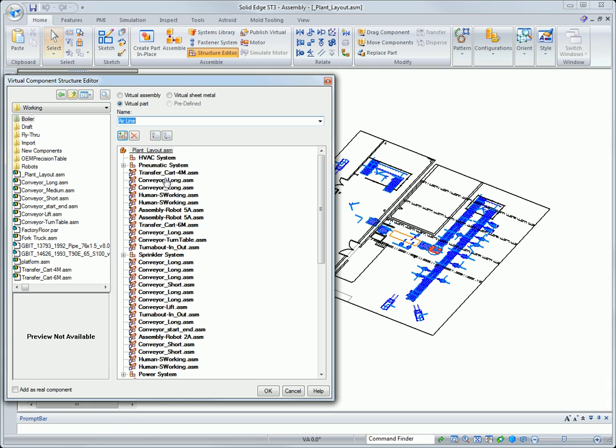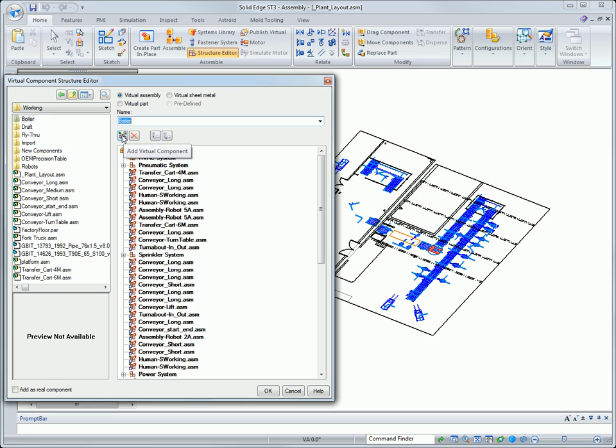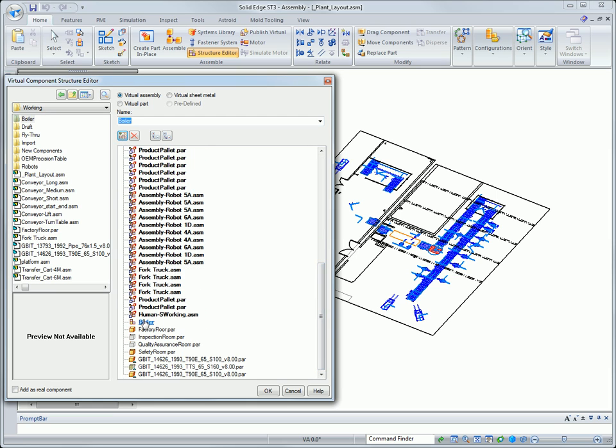If you're working on a familiar design, more often than not you'll have a good idea of what needs to go into the assembly. So why not capture this up front? Think about this. If you were asked to build a bicycle, you'd probably list most if not all the components. That's what virtual components is all about, a tool for jotting down your ideas quickly. We can enter our own part name or choose from a library of components. This library can be categorized by document type, such as parts, sheet metal components, and assemblies.